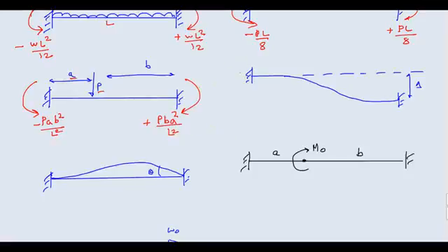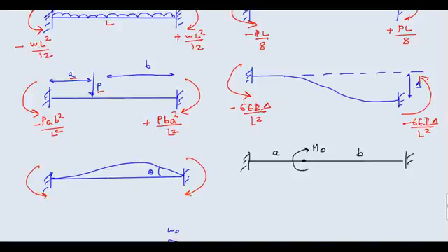Okay, this value here is nothing but 6EI, obviously it is minus 6EIΔ/L², and this value is also negative. Okay, this is also minus 6EIΔ/L². This is a very common one, you must be knowing this. This value here is plus 4EIθ/L. Just now we saw it, when we were calculating stiffness. This is 4EIθ/L, and on the other end this one is minus 2EIθ/L.